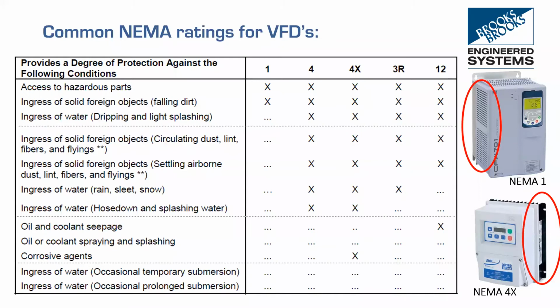And if we're going with something bigger, then what's often done is we take that VFD and put it inside another enclosure, and that enclosure has the NEMA 4 rating. That enclosure usually has to be oversized, so we have a lot of surface area to get rid of the heat, and also have ventilation or even an air conditioning system added. Inside that enclosure, we have either a NEMA 1 or an open style VFD. Yes. And that can get certainly more costly than just a NEMA 1 VFD for the same size. And the lead time also goes up quite a bit, because these are usually custom enclosures.